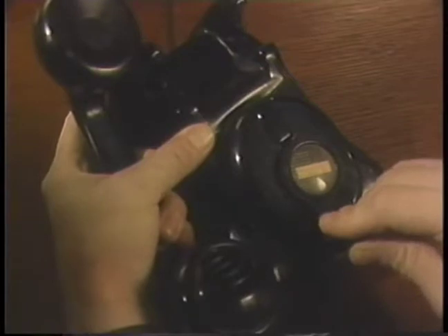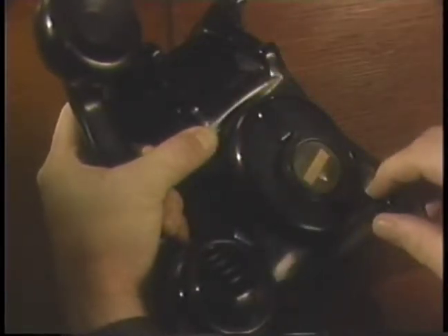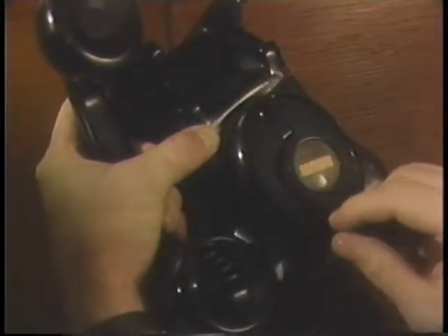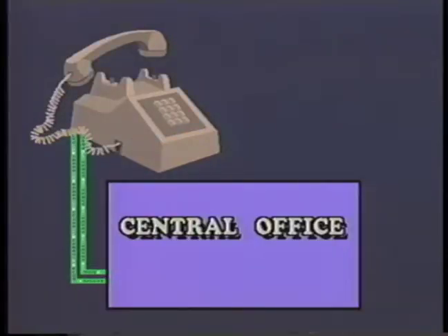On an old telephone, you turn a magneto crank on the set. This generates a current to the central office indicating that you want to make a call. With modern telephones, you lift the handset, the switch hook goes off hook, and the circuit is completed to the central office. This indicates that you wish to make a call.